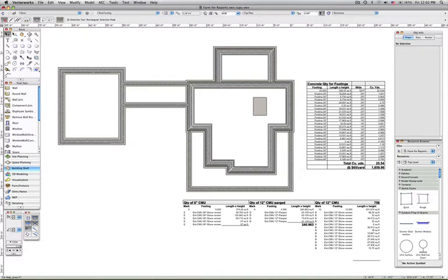Now let's take a look at totaling up the number of concrete block required for the foundation walls. In this project we have two sizes of block, 8-inch and 12-inch, and three types of walls, two utilizing the 12-inch block and one that uses the 8s. We'll use the wall area report again and modify it to yield the quantity of block required for the job.